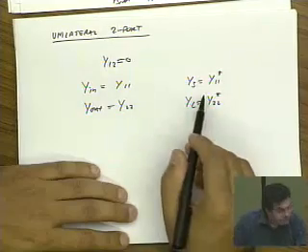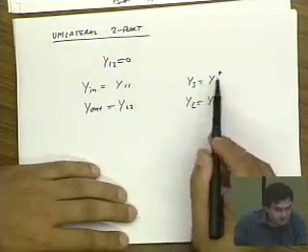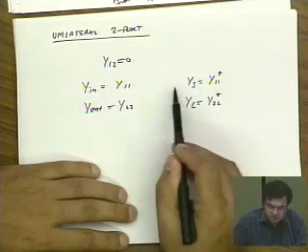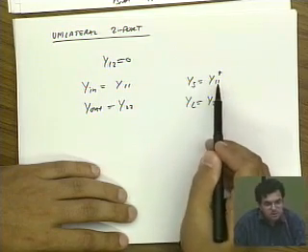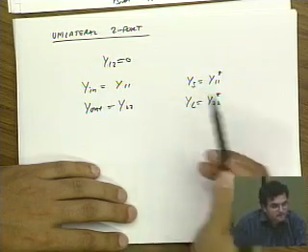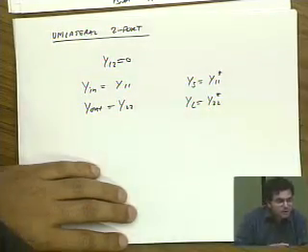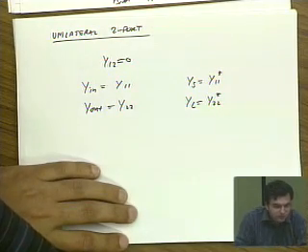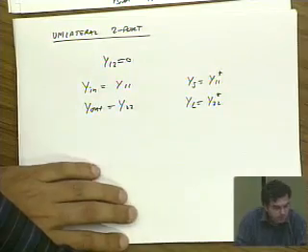Very good. If the device has a negative real part, that's actually unphysical. I can't put a passive source admittance that's the complex conjugate of that, right? I can generate a negative conductance, but that requires another amplifier, and that's not really the problem we're solving. The problem we're solving is we're looking for a passive source and load termination to give us the maximum gain.